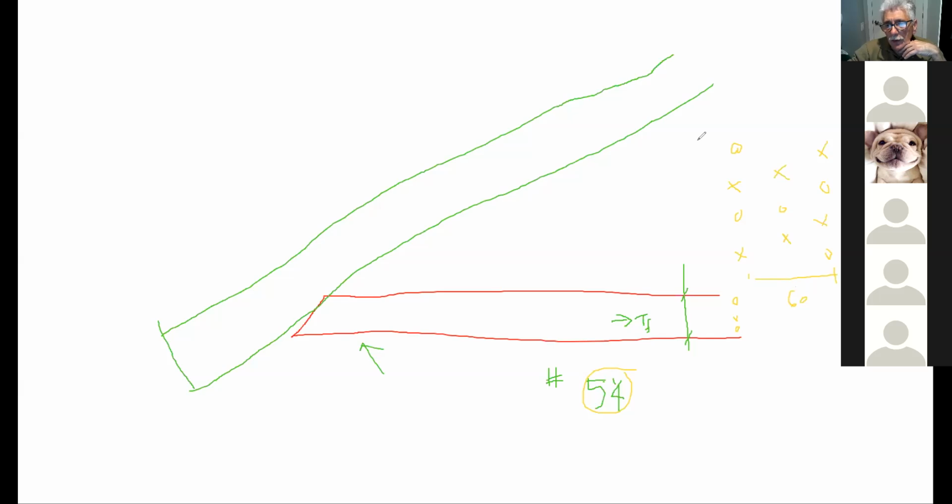And then of course, like these, you're keeping your edge distance, and you figured out that you can put 4. So in your case, you're able to put 1, 2, 3, 4, 5, 6, 7, 8. You're able to put 11 nails, whereas we're only able to put like 5 more nails because you're using 2x6. So Emily, you know that you're working always parallel to the grain.